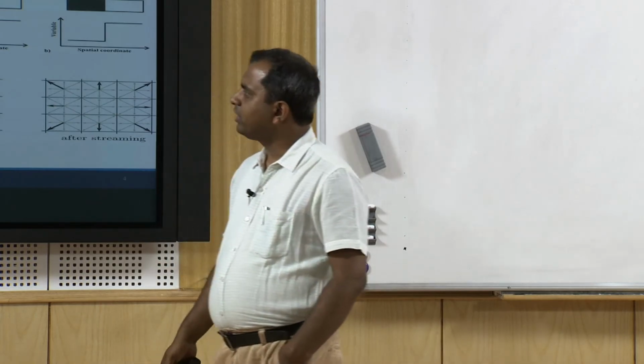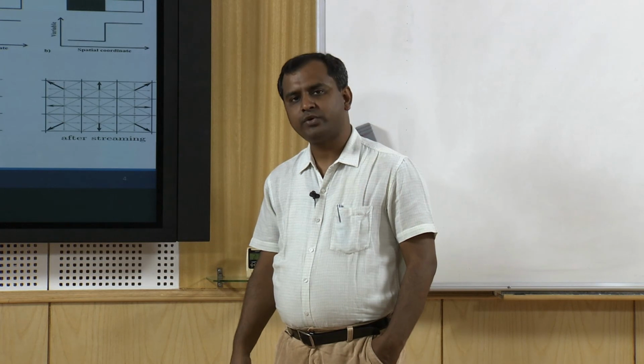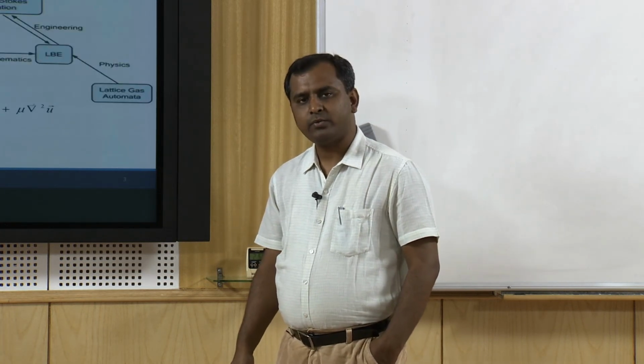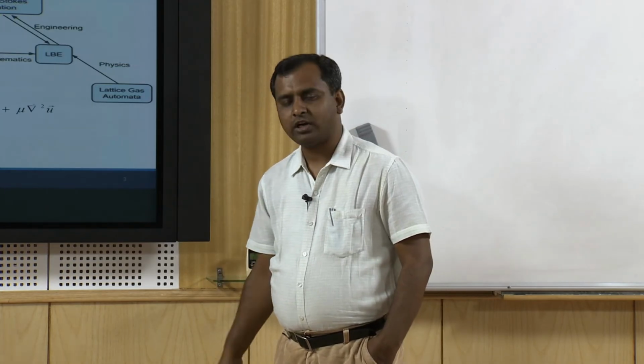So altogether, if energy is involved, we have 4 equations: the continuity equation involving n, the momentum equation, the energy equation, and apart from that we also have one equation called the Cahn-Hilliard equation involving phi.